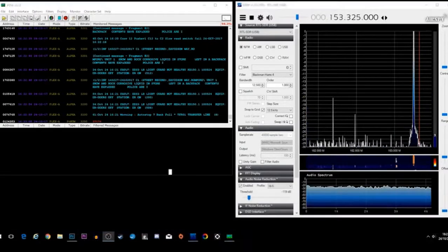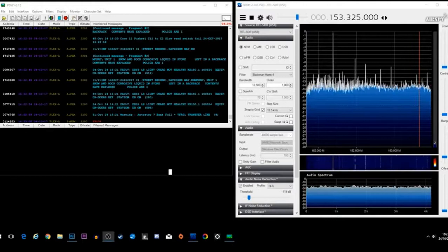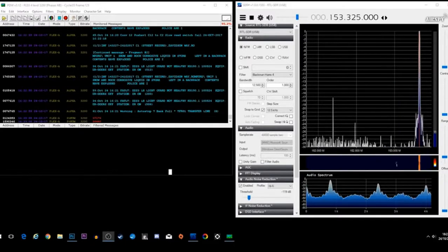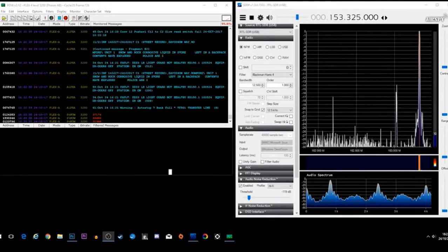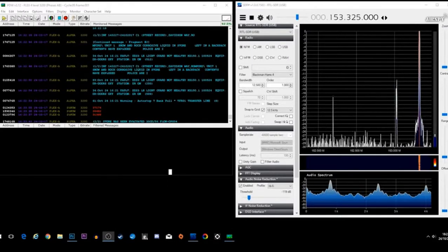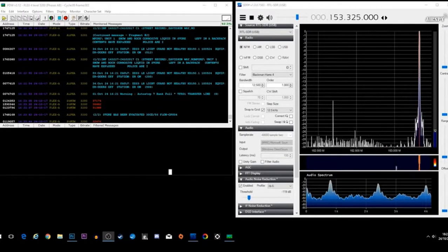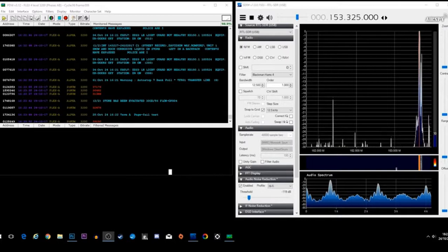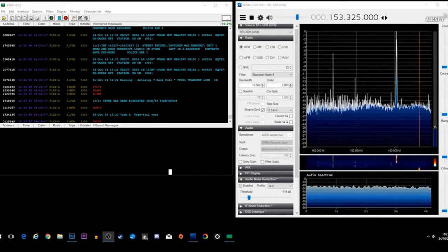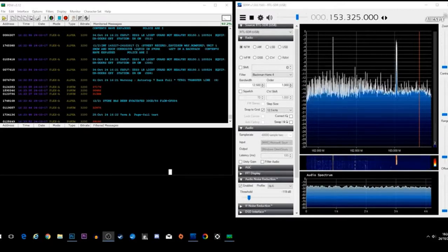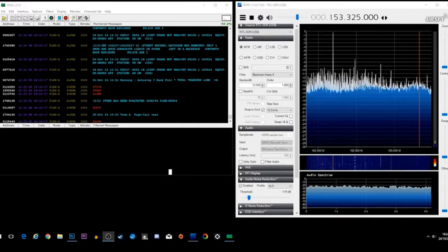As the transmission comes through the SDR receiver and through the software on the right-hand side, the audio is pumped directly into PDW. What PDW then does is decode it into readable text that we can understand. The people using pagers may be doctors and people like that, and there are also a lot of electronic sensors which automatically send data. So I'll let a little bit of the audio through from what the SDR is receiving, just so you can hear the type of tones and sounds that pagers make.